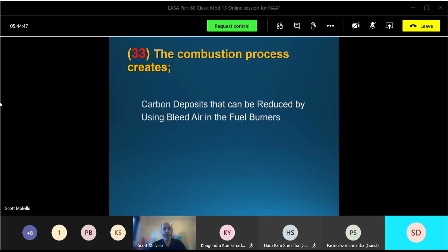If too much carbon builds up on the burners, that can prevent a good flow of the fuel and possibly cause bad starting. Like I said before, you can change a burner, but remember to change it as a complete set where possible. If you do take a burner that's dirty, don't clean it yourself, because you'll probably push some carbon back up into the tiny little holes. So you send them away to a specialist to get cleaned professionally. If you try to clean them, you can sometimes scratch the surface without even knowing it, and that can disrupt the spray pattern.